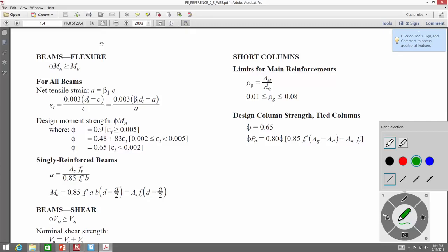It's nothing. This table weighs 5 pounds per foot, more than that, and we're talking about concrete beams. So you could almost just disregard the dead load of 5 pounds per foot. That's a little bit of calculation you can skip.